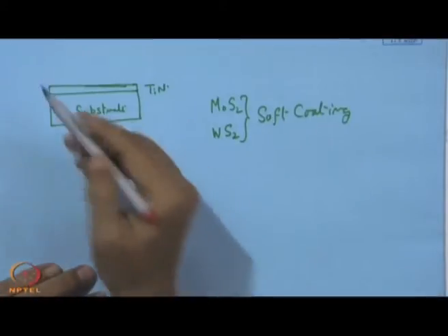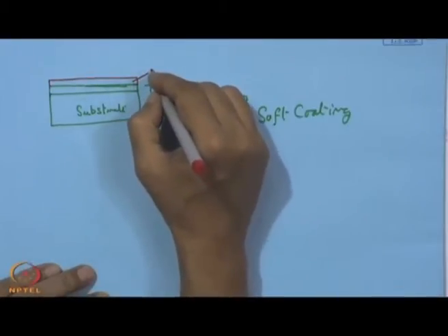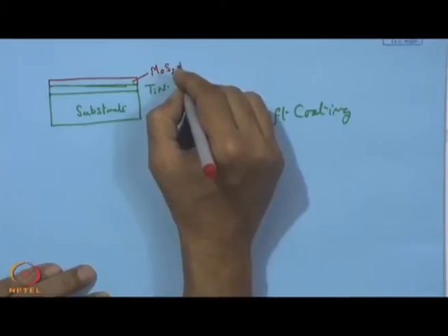Now, this is going to be used on a steel whose surface property has to be improved a lot, and this surface property means it is the tribological surface property. So, obviously our choice will be a super lubricious coating, which we have already mentioned. However, it is found that this coating can be also improved further. What we mean is its performance: if we put a coating of titanium and the deposition is done on titanium, that means this should be now the architecture. So, this is now the architecture, this is MoS2 plus titanium.